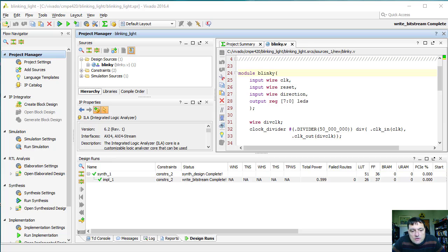Now theoretically I could use an oscilloscope or an external logic analyzer, and I could wire up the scope to the board, and I would be able to see the voltages that are present on the I/O pins. And if I'm not seeing any I/O, all I know is that I'm not seeing any I/O. I know that there's some kind of a problem internal to either the logic of the Verilog module that I've designed, or in the assignment of the Verilog module to the pins, or that there's been an electrical fault.